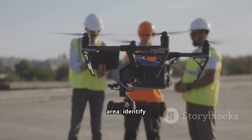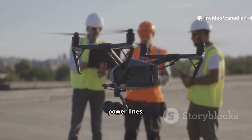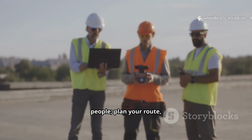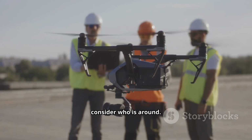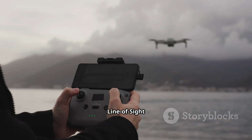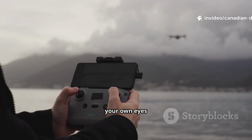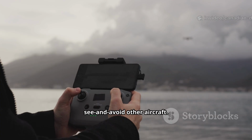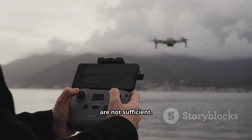Survey your launch area. Identify hazards like people, buildings, cars, power lines, trees, and water. Establish an emergency landing zone away from people. Plan your route, max altitude and distance. And consider who is around. Visual line of sight, VLOS. This is non-negotiable. You must be able to see your drone with your own eyes without binoculars to maintain orientation and see and avoid other aircraft. First-person view, FPV goggles alone are not sufficient.